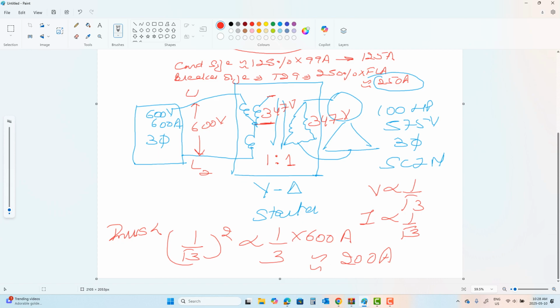The reason why we have motor control stations is because of lots of inrush that they cannot handle by just being given the supply voltage. Motors are not like light bulbs. They have to take their time to get to full speed, and that's the process of inrush which needs to be rectified. And how do you rectify the inrush process? By doing low voltage starting. So you don't start at the same voltage rating as given on the nameplate of the motor.